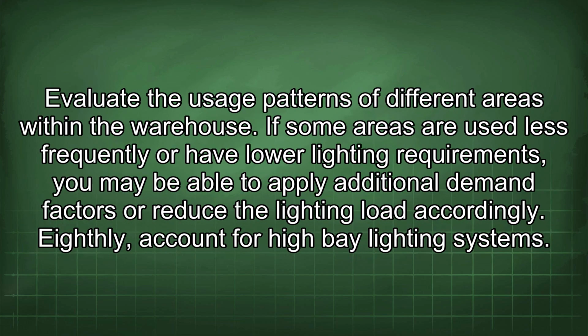Seventhly, consider specific area usage patterns. Evaluate the usage patterns of different areas within the warehouse. If some areas are used less frequently or have lower lighting requirements, you may be able to apply additional demand factors or reduce the lighting load accordingly.